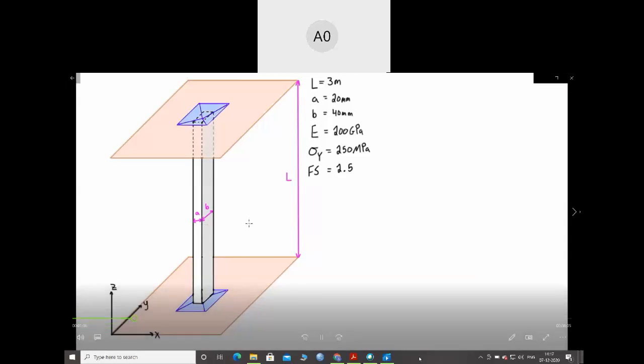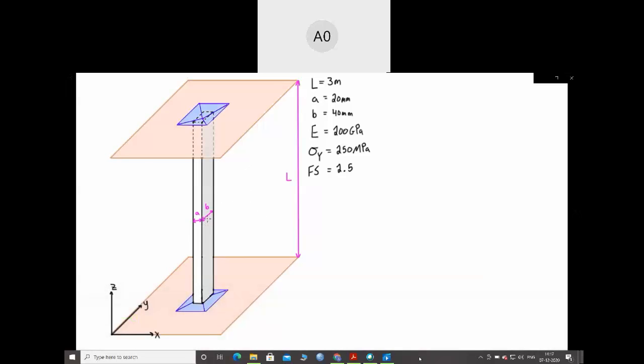So what we need to do is first figure out what our effective length is. Considering both planes it can buckle in, it's considered to be pinned in both of those directions, so our effective length, no matter how we look at it, is just the actual length of the column because it's that pin connection. That came from the previous videos where we talked about different end connections, and in the next videos we'll do different examples. So for now, effective length is equal to the length where we have a pin-pin connection on this column.